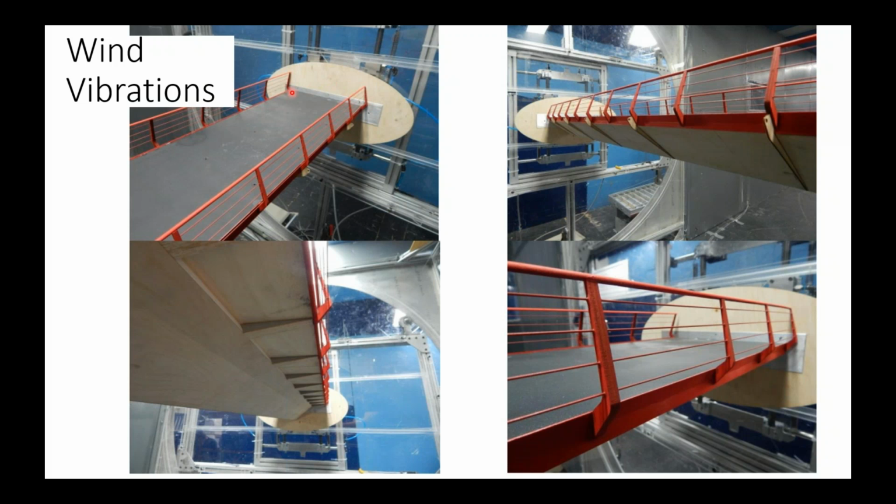In addition, probably the most key feature of the wind tunnel test is the setup in the stiffness. They've got springs back here in the connection of this to their wind tunnel that are scale models of the stiffness of the bridge that we gave them as input to their design of this model. So the structural model tells them what the stiffness and the frequencies of vibration are of the bridge, both vertically and also in torsion, because we know torsion on this bridge is a key feature.